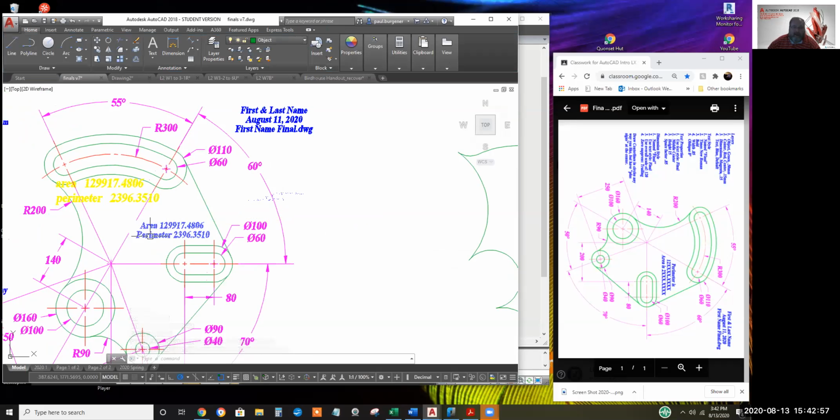Apparently this is masking. Let me double check. I'll reach in. Okay, let me move it. There's a way on text you can mask text so that it whites out everything that's behind it. And the way you do that, there you see it whited out a little bit of the object and the dimension line. That's a property of this text.